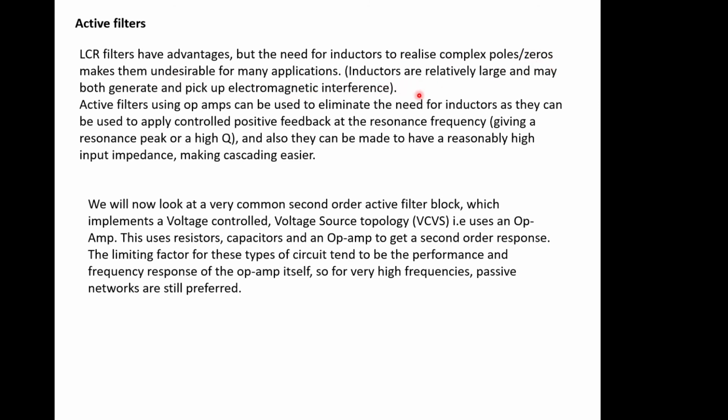As a general rule, circuit designers don't like inductors because they look like antennas, and also they have a lot of weight and mass to them in comparison, and so can mechanically be difficult over a period of time. They can break off because of mechanical moments and things. But anyway, people don't tend to like inductors. They're also difficult to make to known accurate values, so they tend to be expensive.